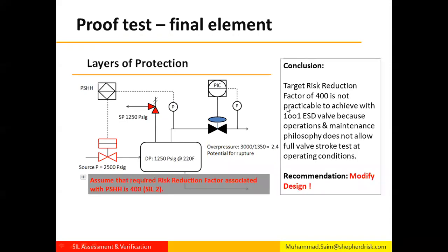So we conclude that the target risk reduction factor of 400 is not practicable to achieve with 1 out of 1 ESD valve because operations and maintenance philosophy does not allow full valve stroke test at operating conditions. Hence, the recommendation is to modify the design.